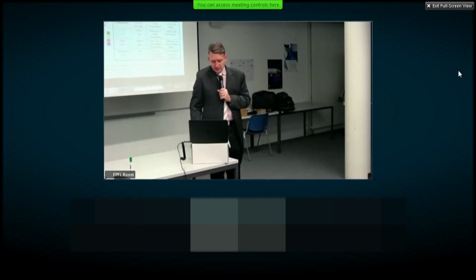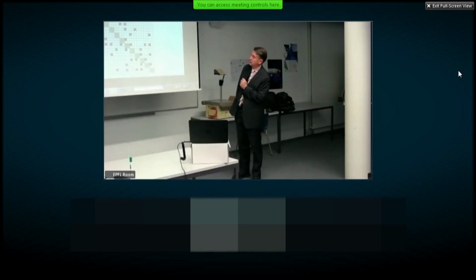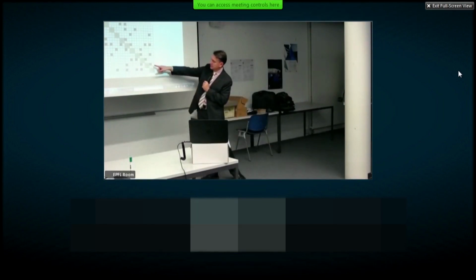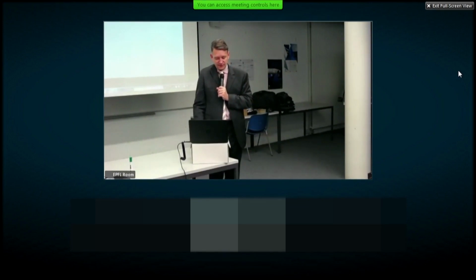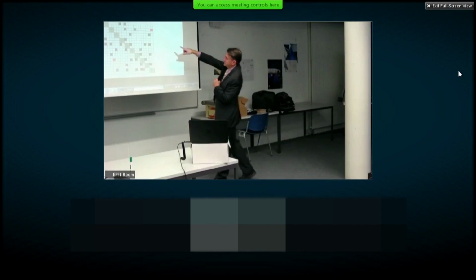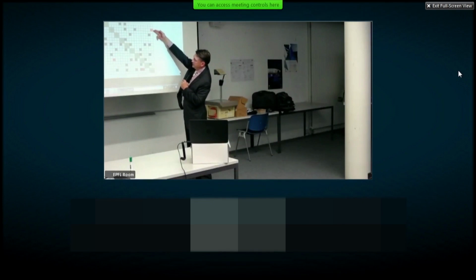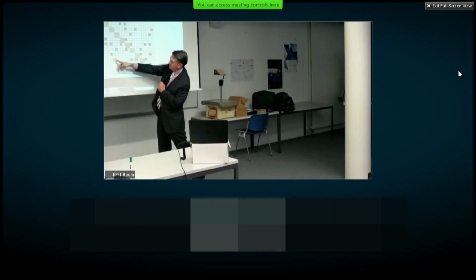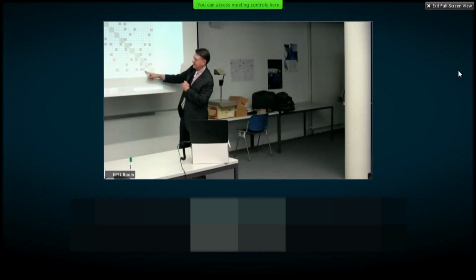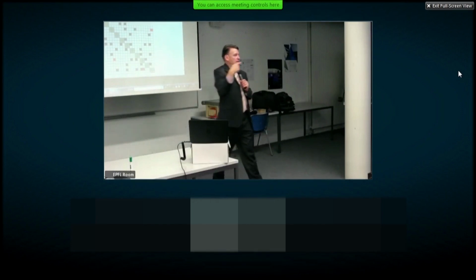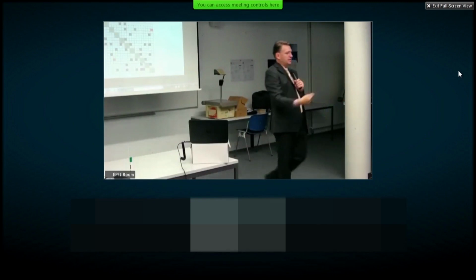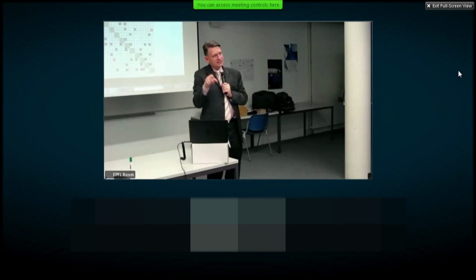So if we apply that idea to the refrigerator, here's our 10 by 10 physical connections. So we have a design structure matrix with only the black marks, so it's symmetric, and this reflects the liaison diagram. And then we can add on top of that the mass flows, which are in red. The way you read this is we have mass flow from the compressor to the condenser, okay? And then from the condenser to the evaporator, and then from the evaporator back to the compressor. You see that? And we could rearrange these to be closer to each other. We could regroup the DSM. But essentially, these red marks represent the cooling, the refrigerant cycle within the refrigerator, within the machine. So you can check by tracing these from row to column. You can actually check whether the loop is properly closed.